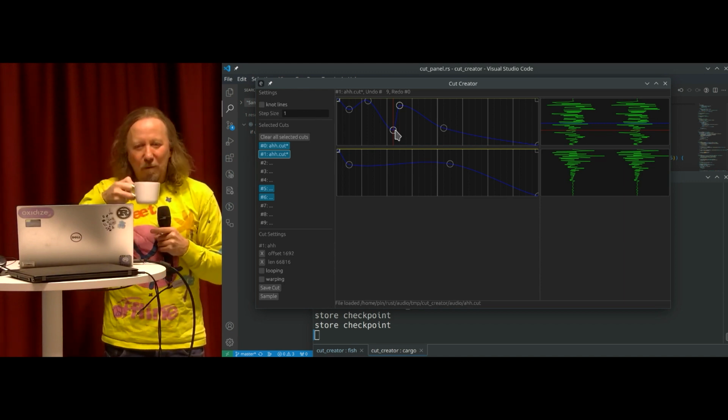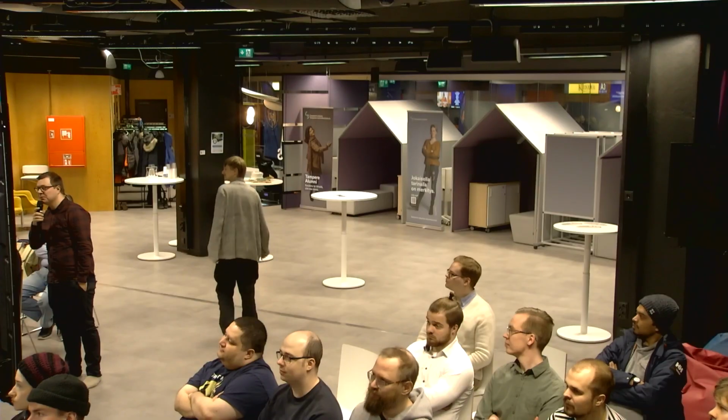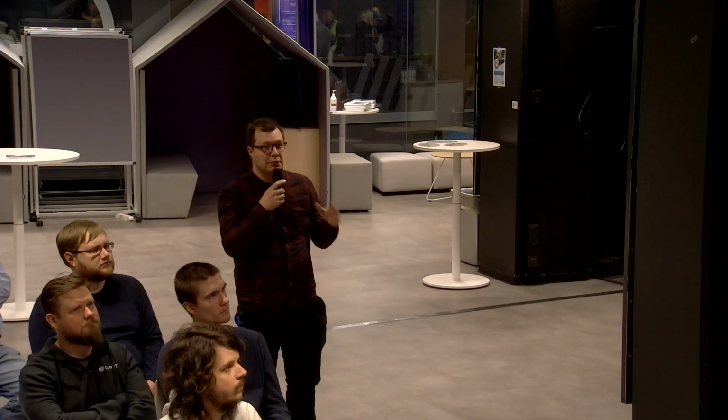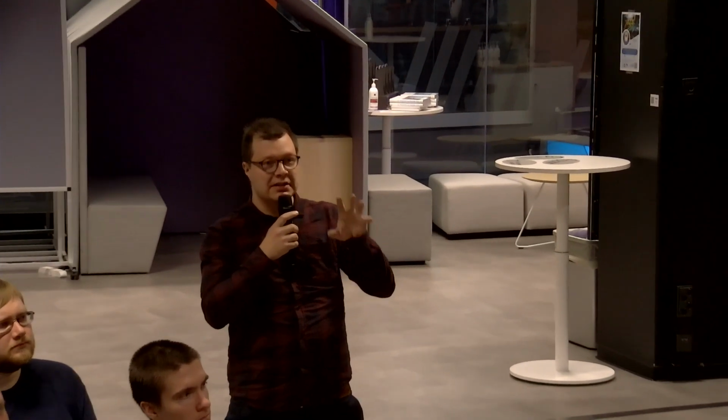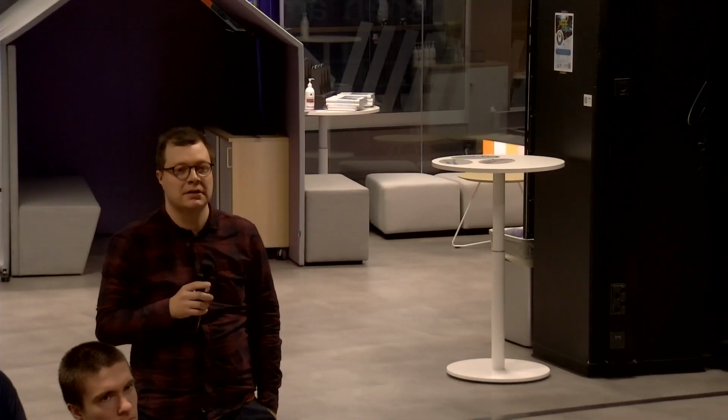Amazing presentation. I just want to ask about the basics from the beginning. Did I understand you had a picture where you had these two sine waves with a phase difference, and the frequency was increasing to the right? Yes. And is that what you put on the vinyl? So you have a vinyl with left and right channels? On the vinyl, you have just a fixed frequency. So like 1 kilohertz is good, because then it allows you to push the record 10 times faster than nominal speed and still be within the limits of what a magnetic cartridge can pick up.